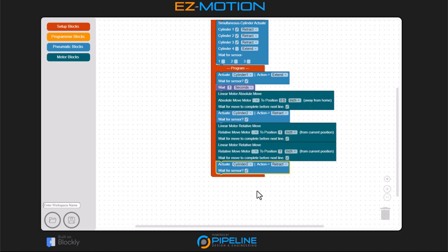Function blocks may be dragged out of the master block at any time. If a function block is left in the white space in the workspace, it will not be active in the saved program sequence, but will remain available to the user for later use. Simply drag the function block back into the master block to reactivate it in the program sequence. Should you wish to delete the function block, either drag it into the left column and release it, or into the garbage can icon at the bottom right corner of the screen and release it.